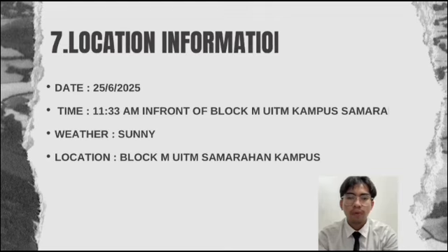For the measurement condition, the sound level meter was mounted on a tripod above the ground. It was set to dBA and LEQ mode, and the stopwatch was used to measure required monitoring period. Measurements were taken in the dry, calm weather, away from reflective surface, while avoiding nearby movement and conversation to ensure accurate and reliable noise reading.